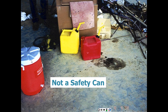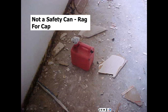These are definitely not considered to be safety cans because they do not satisfy the previous conditions. So you cannot store flammable liquids in these. That's another example of a non-approved container for flammable liquids. In this case, it's covered not even with a cover but with a rag for the cap, so that's a double whammy.